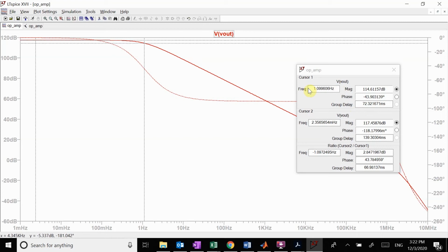Well, you're probably saying, well, that's a pretty dumb amplifier. How many applications have a frequency less than 1 hertz? This is only going to work for DC applications. How are we going to use an op amp for anything useful? So we need to talk about what happens to the bandwidth when we add in stability. It has to have a low corner, otherwise it can't have a high gain and still be stable.